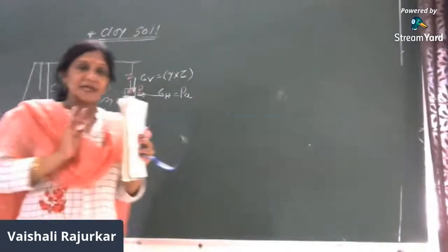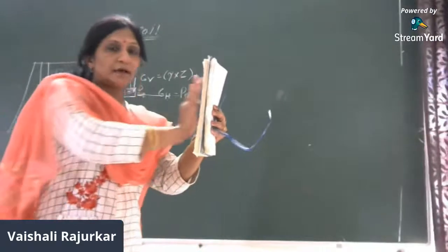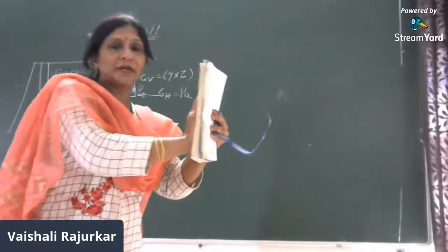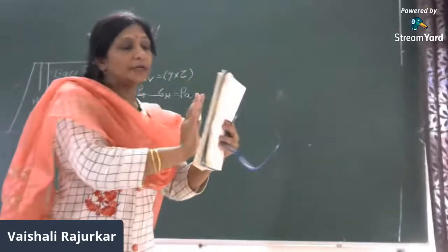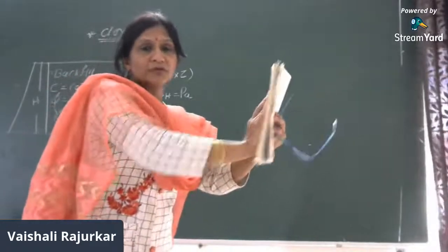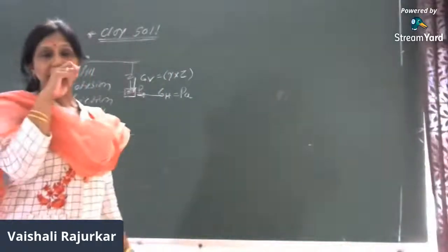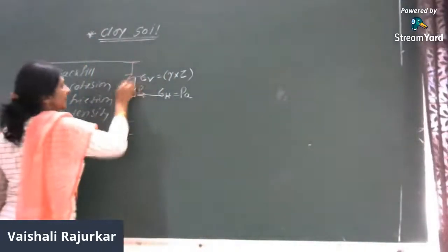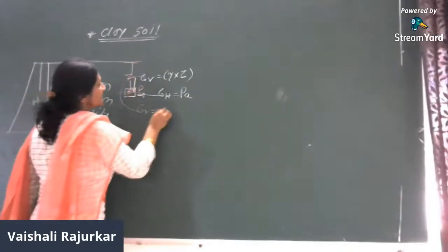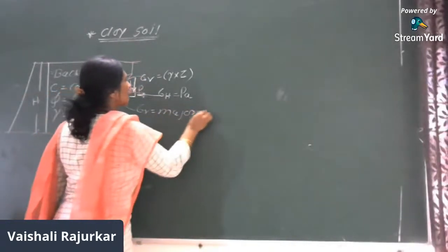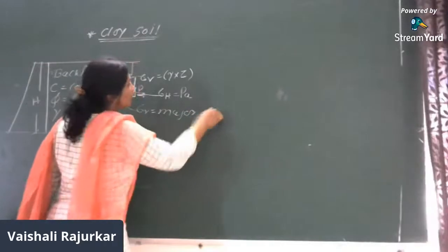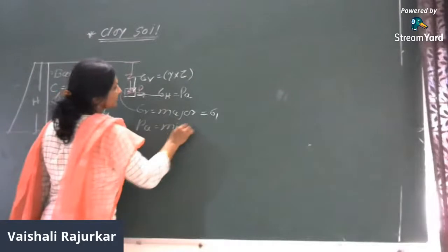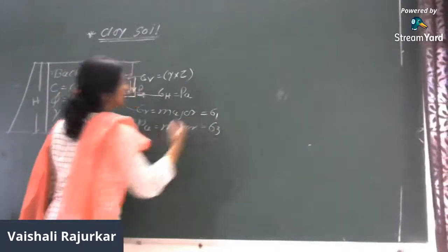As it is active earth pressure, and we are considering the wall moving away, pushing the backfill like this, as there is a movement of the wall, the pressure PA is getting released. Therefore sigma V is considered as major, which is equal to sigma 1, and PA is considered as minor, and that is sigma 3.